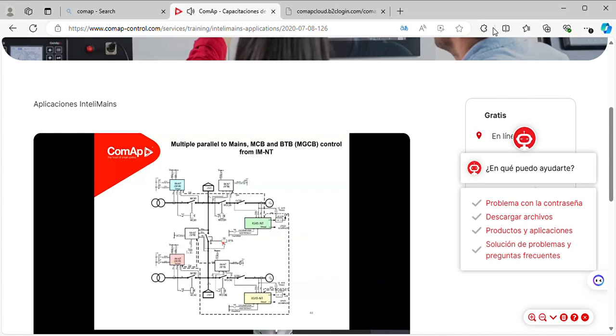There can be examples where we can combine MCB and MGCB application, but again with individual controllers, where you have a high voltage system and you are putting up a transformer in here and you want to isolate this transformer outgoing from the common bus. So you can put a bus tie breaker here. So we can further cluster them into 3 bus tie breakers. So there is another illustration for that, but the overall principle of operation still remains the same.